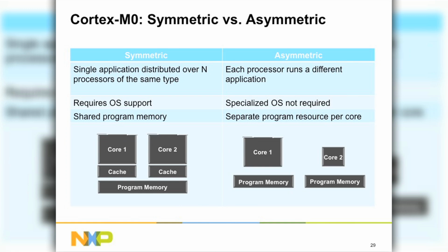What this shows here, though, is the difference between symmetrical dual core and asymmetrical dual core. Symmetrical dual core is what you think of when you have that quad Pentium, 4 things that are dividing up a complex task equally, and they're all running and dividing up one task. That's not what our dual core is. We actually have sort of a big-little approach, and the little, the M0, can handle those I/O capabilities or things that require less power, while the M4 is either asleep or chugging away at something more important. So an asymmetrical dual core has 2 cores that are of different sizes and/or different capabilities.